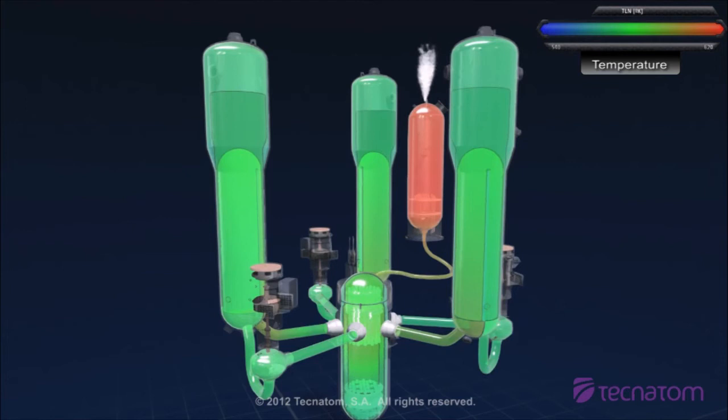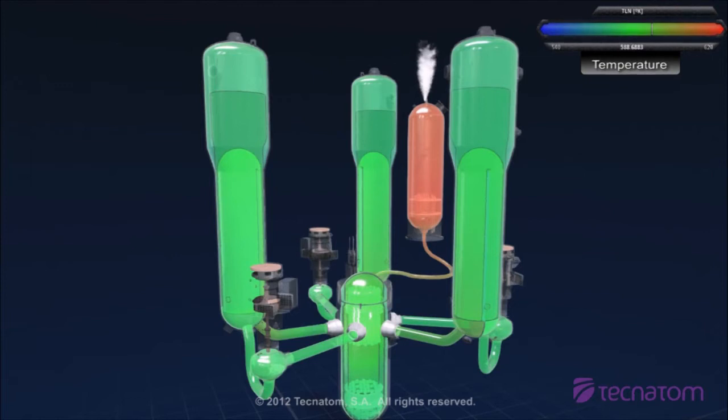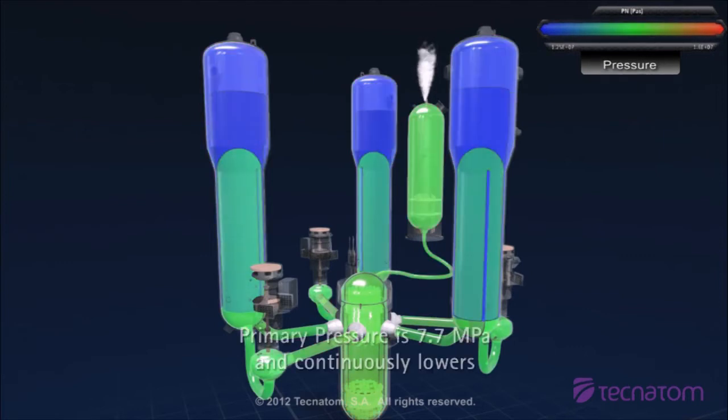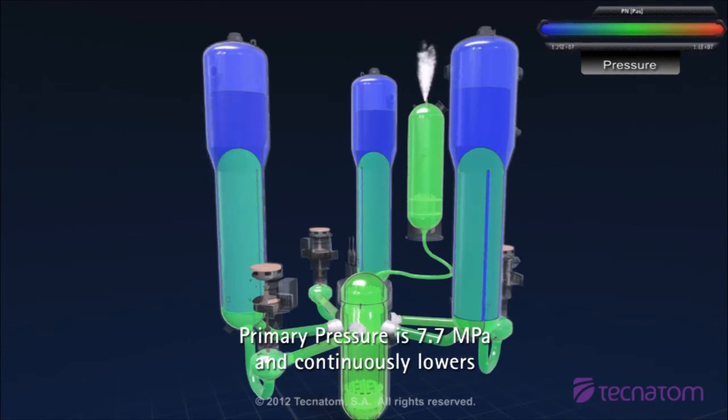Now we can see how temperatures have dropped after the trip, and temperature difference in the steam generators is 8 Kelvin. After the reactor trips, primary parameters should stabilize at the normal no-load values. However, relief valve remains open when pressure lowers below the set point. That is causing a continuous drop in the primary pressure. Normal pressure is about 15.4 megapascals, but pressure at this moment is 7.7 megapascals and lowering.